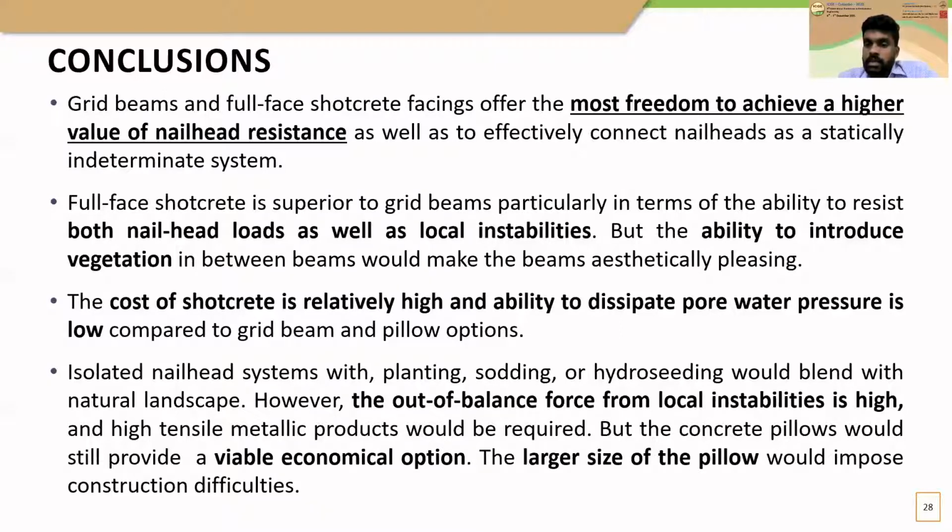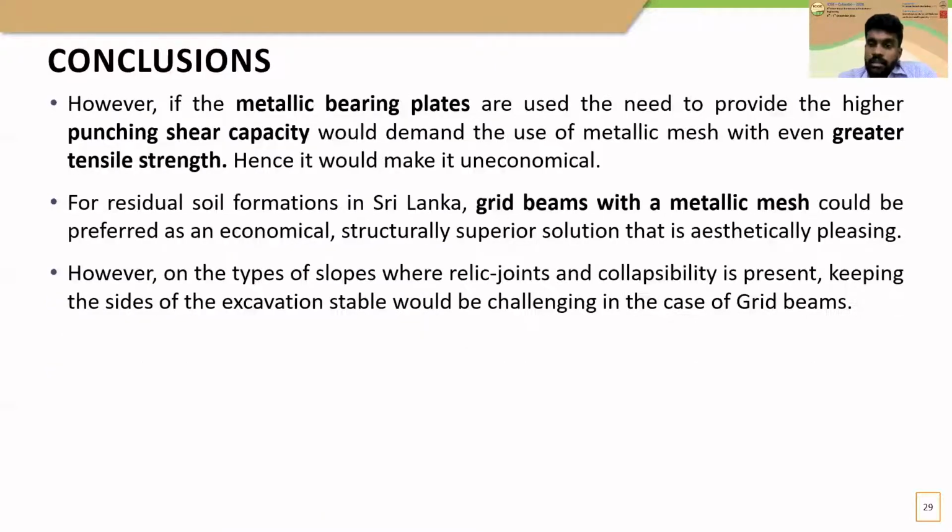However, the out-of-balance force from the local instabilities is high and high tensile metallic mesh would be required. But the concrete pillows would still provide a viable economical option. The larger size of the pillows would impose construction difficulties. If metal bearing plates are used, it would demand the use of metallic mesh with even greater tensile strength, and it would make it uneconomical.